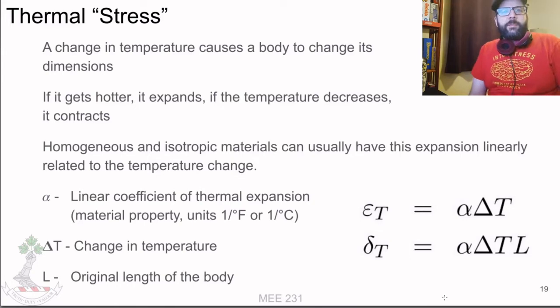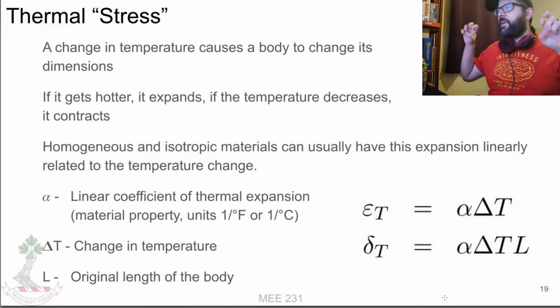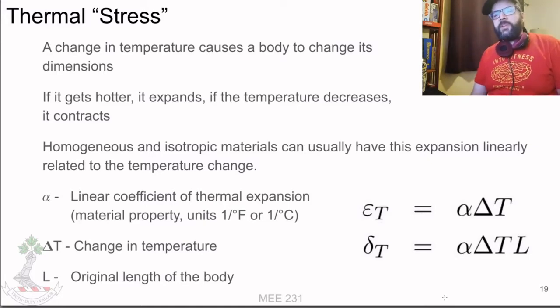So one other thing we want to be concerned about is what we call thermal stress. I put stress in quotes because really temperature changes cause strain. There's a thermal strain, and sometimes that strain causes stress in the body, but it doesn't directly cause thermal stress per se.